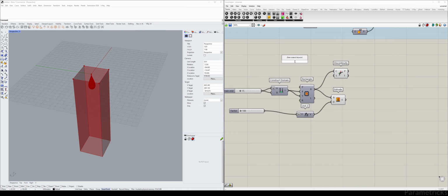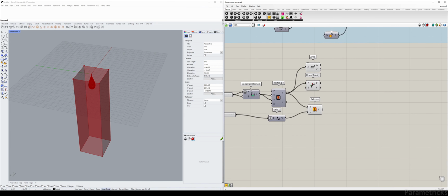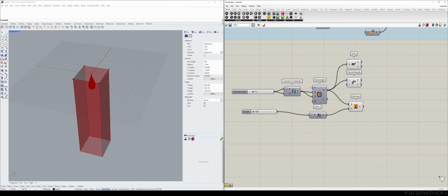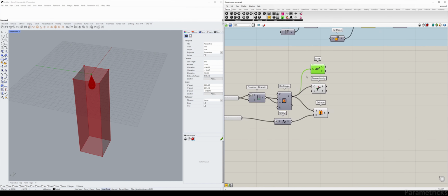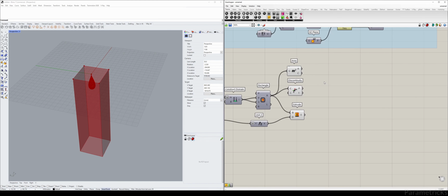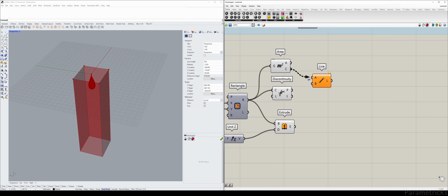And then what I'm going to do is take an area, because I want the center point for that. You can also do average, I believe, or just center, but I've gotten used to using area, or you can just use the original point since it does come from an origin point, which is similar. But this one means that whatever you put this, doesn't matter, I always get the center of my rectangle, or actually square. With that being said, let's make a line of 2 points, obviously from the C to the P, so we got that one.